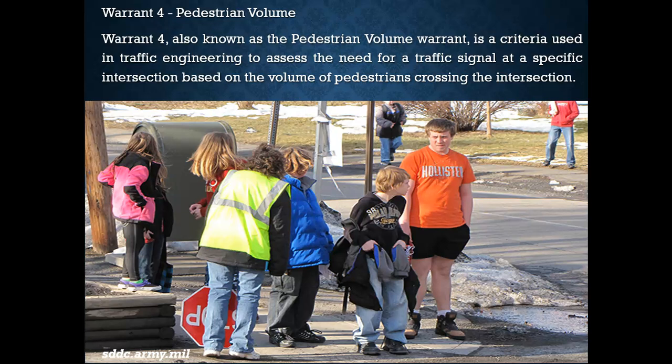Warrant 4 is also known as the pedestrian volume warrant. This is a criterion used in traffic engineering to assess the need for a traffic signal at a particular intersection based on the volume of pedestrians crossing the intersection. If we have a location where the average number of pedestrians crossing the road is 100 or less, it cannot be compared to a pedestrian crossing where we have over 1,000.